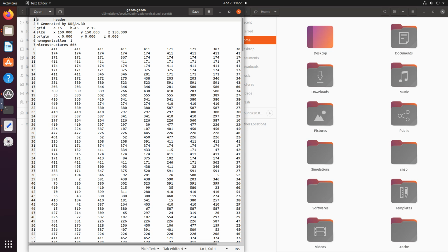The advantage of this is that the simulations will be much faster because the RVE is much smaller. If I do the same calibration on a larger RVE, it would take weeks. Here, it would take minutes. So I use a small RVE so that my simulations run faster. I have less data to process, so that I can quickly compare results, reiterate, and quickly process, right?